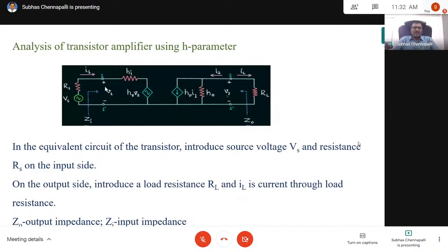Then you work out the source. You can have RB here, and the circuit on the left side can be worked out like this. I say that your RB is absorbed in this resistor, and accordingly the voltage source is also modified. So not to complicate things, I merged my RB here with the source resistance, and finally this is the equivalent voltage source.